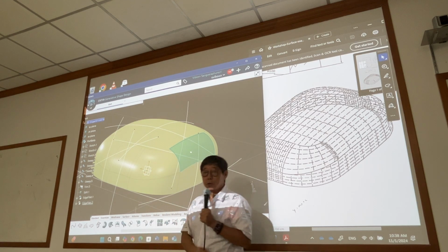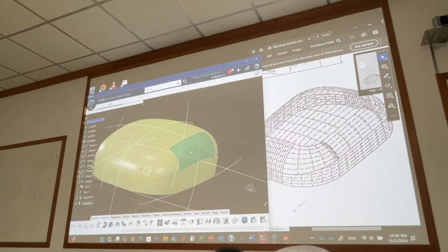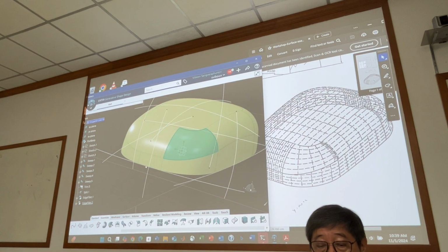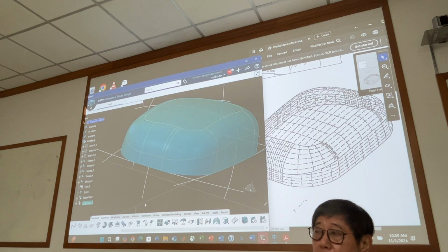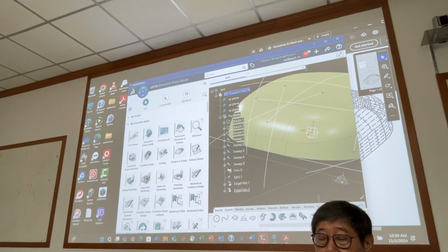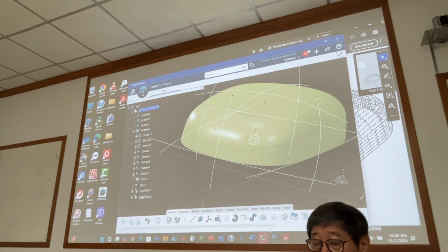This one, the whole entity is formed in one because of the fillet. See, if you want to add thickness, you can do this. You have to go back to Part Design in Generative Shape Design, and thickness, this one.